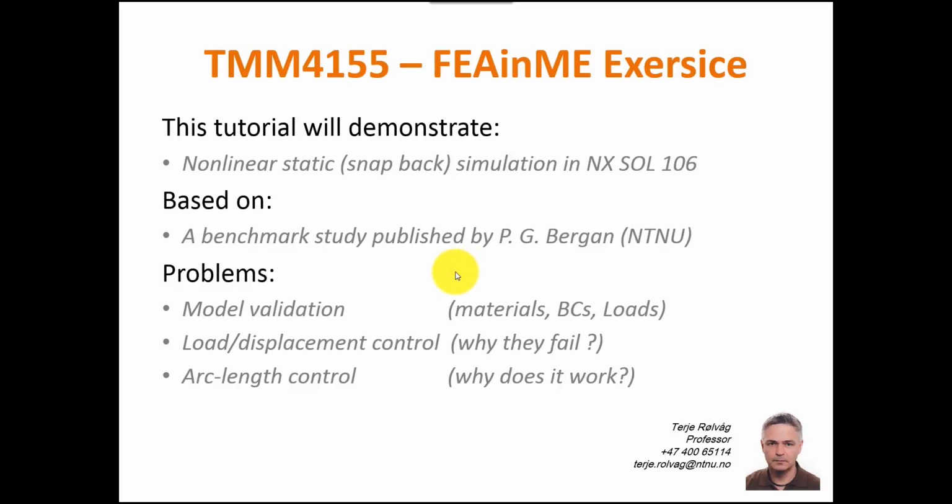First, I will show you some model validation, how you can ensure that the model has the right boundary conditions, loads, and materials. And then I will show why load and displacement control will fail. And I will show you how you can use the arc length control to guide the solver through the numerical problems.